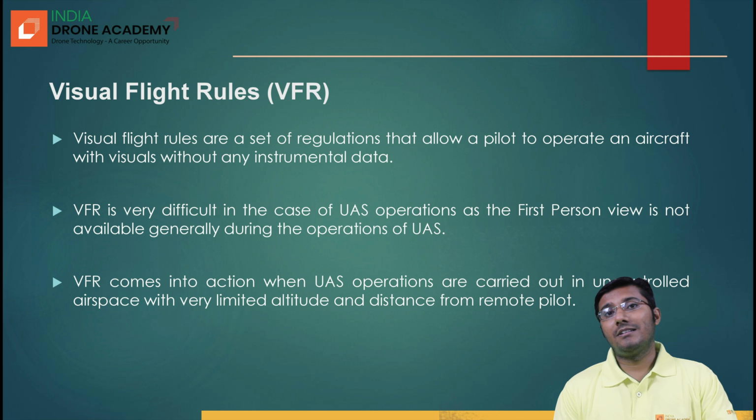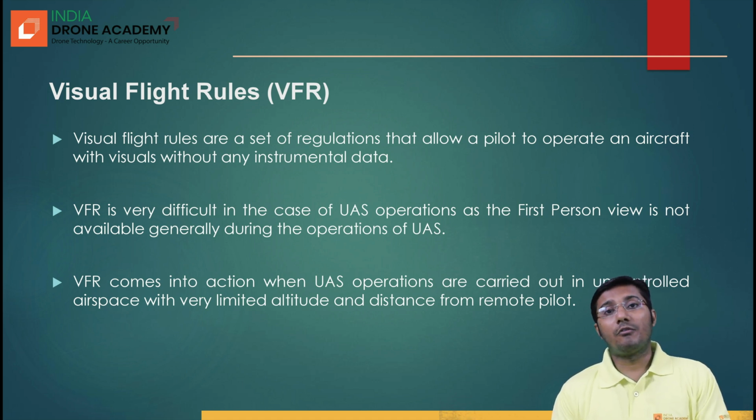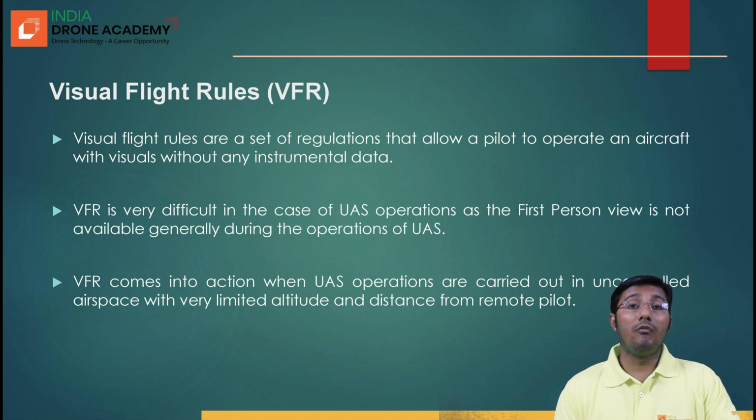The moment this aircraft enters the flight information region of Delhi, the flight information region of Mumbai will hand it over to the Delhi flight information region. From there onwards, the Delhi flight information region will be responsible for providing the relevant information affecting that flight. Then the moment it enters the area control service of Delhi airport, the Delhi flight information region will hand it over to the area control service of Delhi,